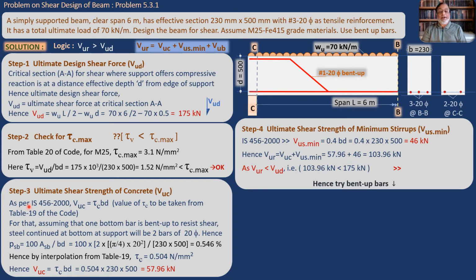We have seen already in the earlier video that we have to provide some shear stirrups in minimum quantity. Whether required or not, we must provide shear stirrups in a beam. Here we have not designed the beam, so you see this beam without any shear stirrups drawn. Actually, this is never the picture of a beam because you always have some shear stirrups in the beam. Whether required technically or mathematically or not, the IS code has compelled us to provide some minimum shear stirrups.